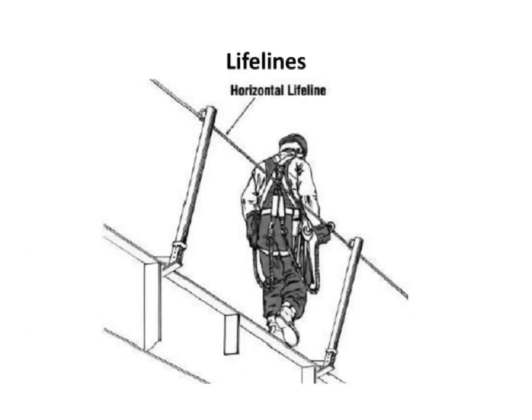Lifelines are a vital component of any work undertaken at a height. Horizontal lifelines provide a secure attachment point, enabling personnel to ensure their safety when ascending to a higher surface. Such lifelines are often used with other forms of safety equipment to reduce the risk of falls. It is essential that all lifelines are first tested and safely affixed before use.